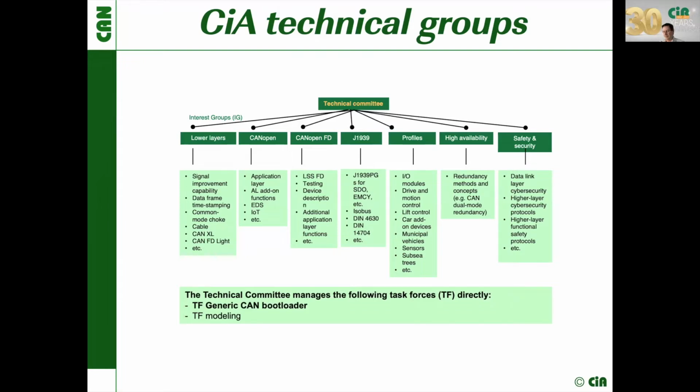that we have a lot of working groups and they are working on a lot of documents. They add new functionality, and there's often a requirement maybe to handle new functions, to remove detected errors, or to react on new requirements, maybe security requirements, to update the local firmware of devices that are already deployed in the field. And we have already, since a couple of years, a document that describes in principle how the bootloader functionality should be handled, the firmware update over the CAN interface should be handled.